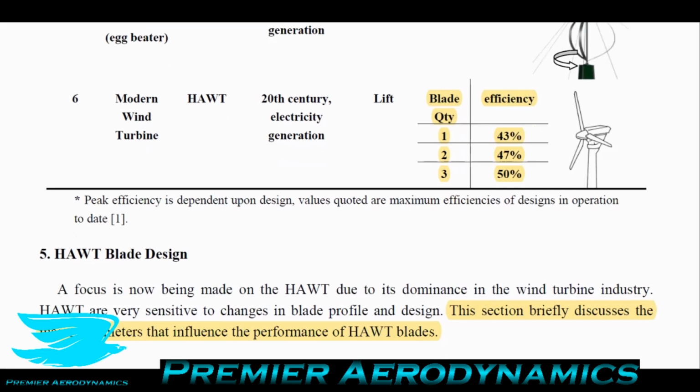So speaking of efficiency, I'm going to quickly pause here and talk about how, if you want to increase the efficiency of your wind tunnel experiments, you need to make sure to measure the density of the air that you're using in your wind tunnel. We've been talking about wind turbines too much. The reason that is important is because the density affects everything in your measurements. It affects the Reynolds number, and it even affects the wind tunnel velocity. So if you want to determine what the wind tunnel velocity is, you need to know what the density is. And the density can change 2 or 3% on a regular day.